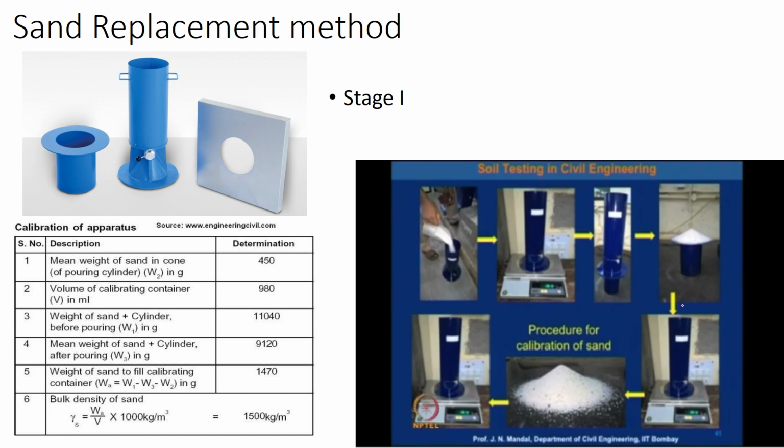See, the tendency of sand: you just take sand and pour it on the ground. What is the shape it makes? It makes a triangle. When you pour sand, it makes a triangle. We call that the angle of repose. That is, the sides of the triangle form a particular angle. When you keep on pouring, after forming that angle, the sand particles will start rolling down the sides. So it's like a constant: the triangle which is formed will have a constant angle, which we call the angle of repose.